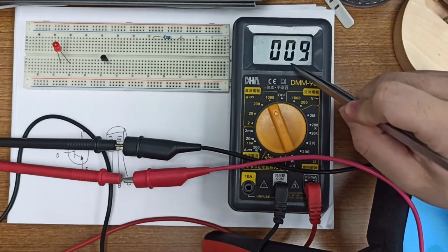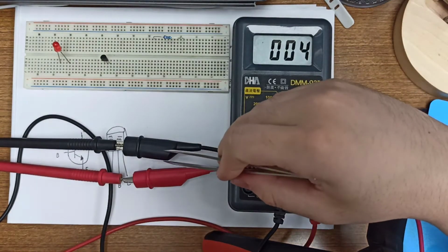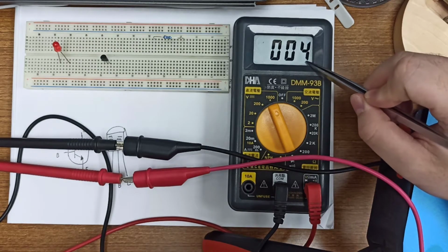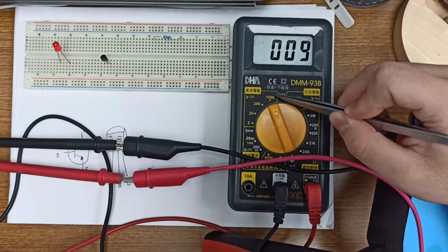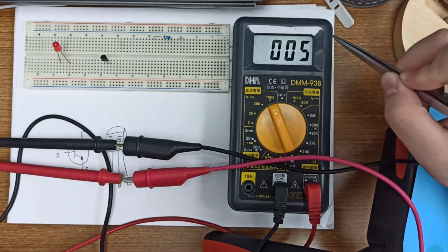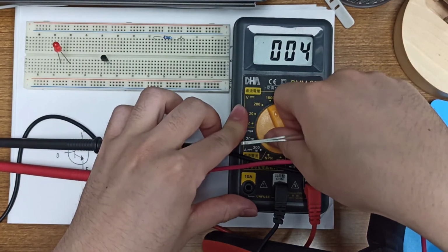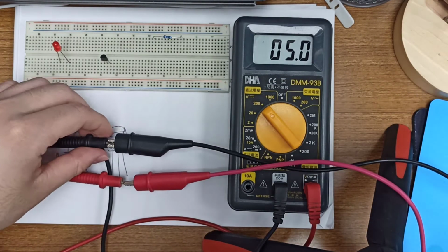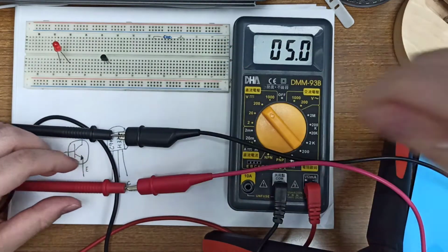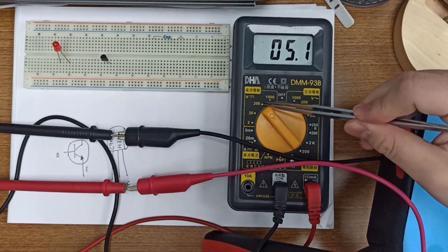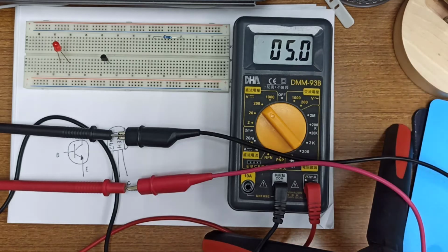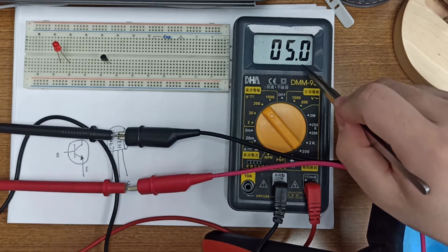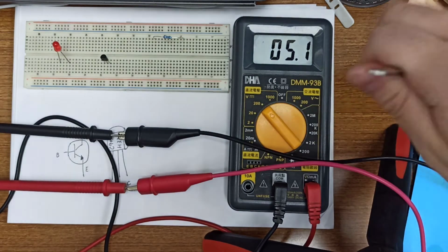See, what does it mean? This one, we input 5 volt, and this one means 0.005 volt. Since the level is too big and the precision too low, maybe we change to another level, 200. So what does it mean? Oh wow! Alright, wait a moment. Okay, if we change it to the 200 level, we input 5 volt from this power supply, and this one is 5.0 or 5.1. Yep, it's correct, right? So we measure the 5 volt.